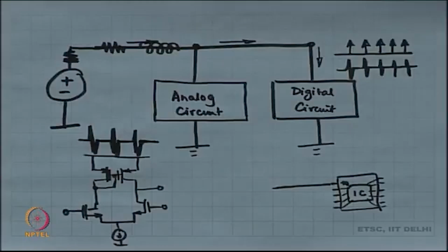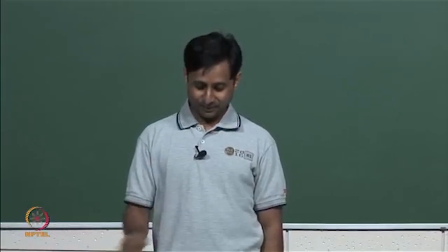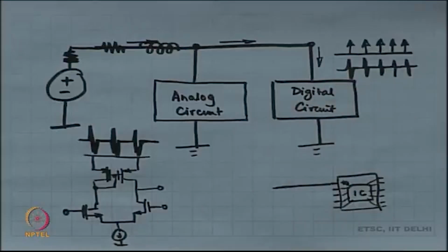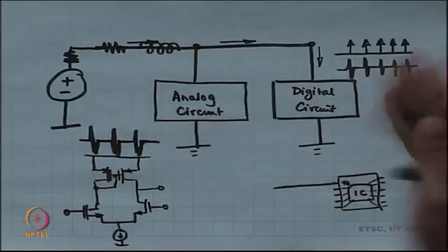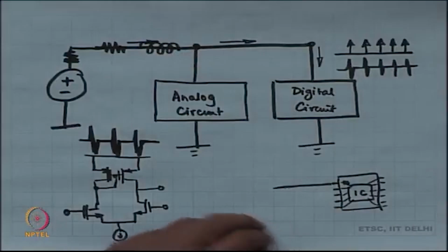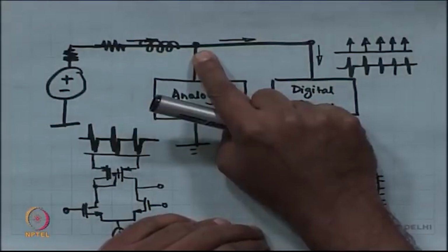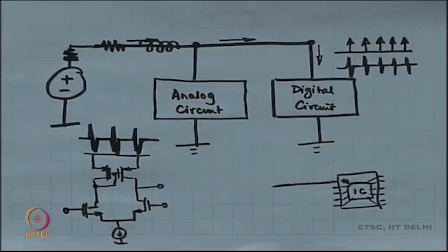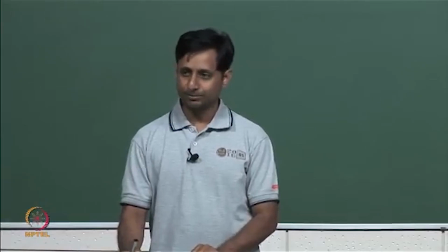So, this is a problem, right, and whenever there is a potential problem, Murphy has said that that problem is going to crop up in your life. Okay. So, I am identifying this as a potential problem, and guess what, this inductance in the power supply wire is everywhere, all right. So, we have a problem. The problem is that the power supply to the analog circuit is not good, it is not the VDD that you want, it is not a constant voltage.